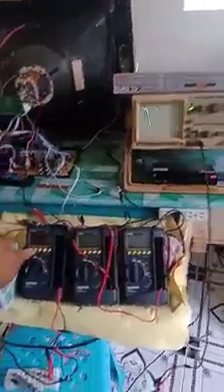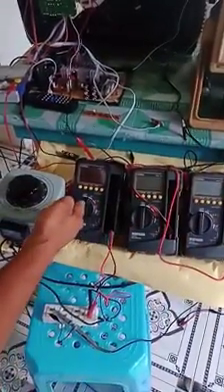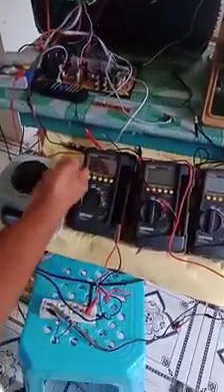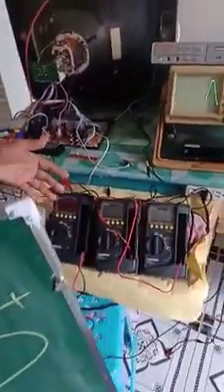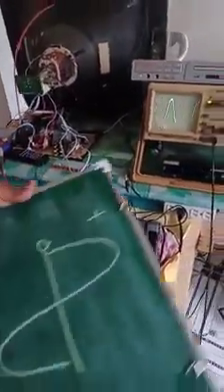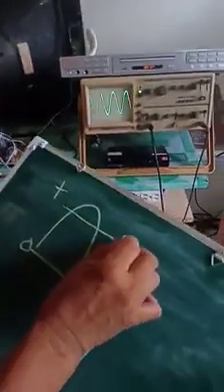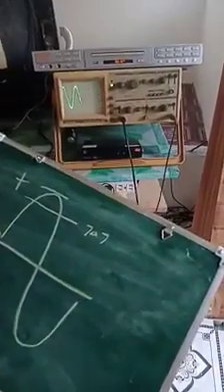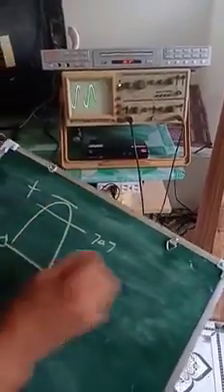The 220 volts, which is now at the outlet, we measured the voltage at the outlet, and the tester registers 220 volts. That 220 volts is the measurable voltage by our tester, and it is actually the effective value. It is only 70.7% of the peak value of the amplitude.